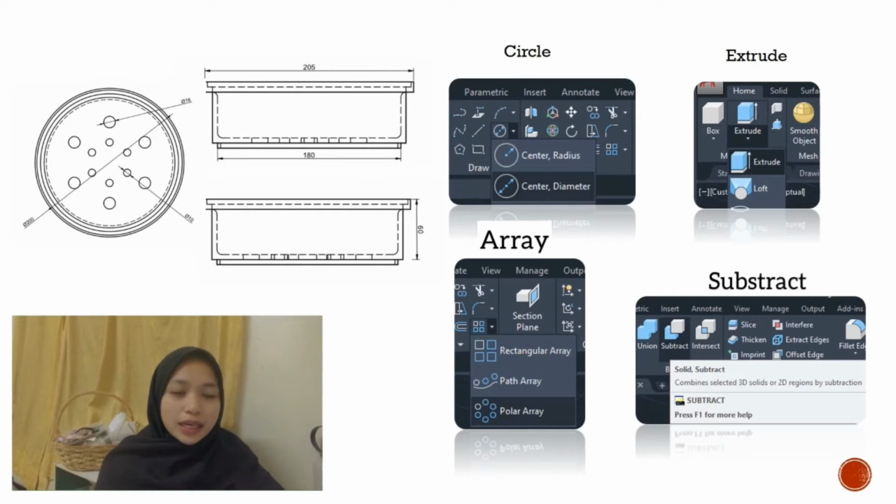Next, I want to make a hole of the symmetry, for which we just use the command array. First, we make a new circle of 8.5 radius and put it below the object. We extrude the circle at 10mm and then subtract it from the object. We can use the command array to make the holes of the symmetry.